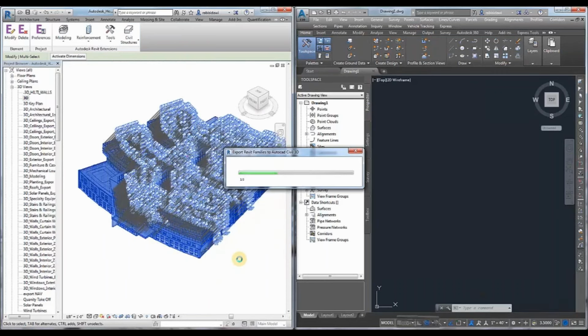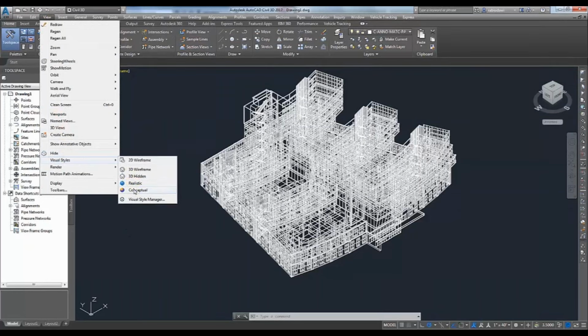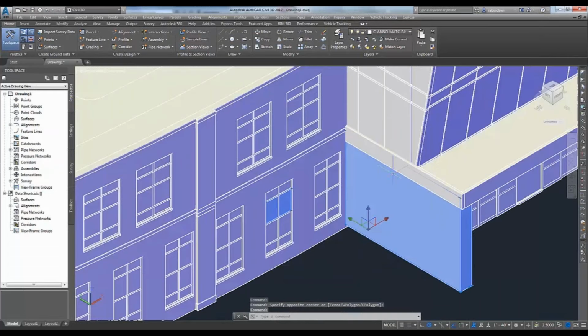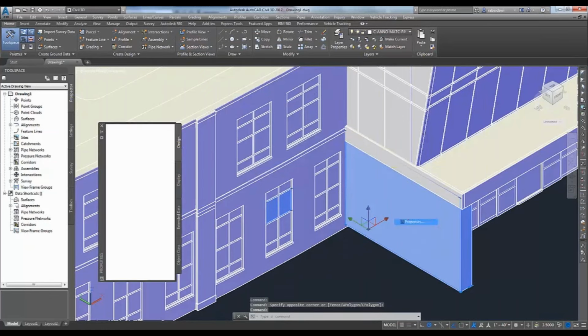as a cube. So here we have even a Revit architecture file that's been transferred into Civil 3D. Not only the structural part is transferred, but also all your walls, doors, windows, even furniture, everything gets transferred, and it's created as a solid, which is fine.